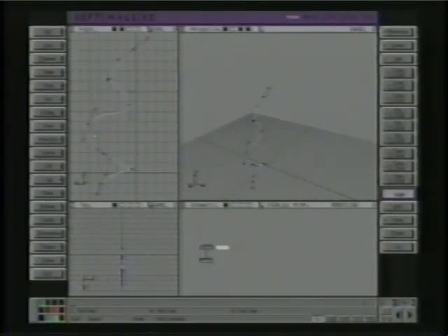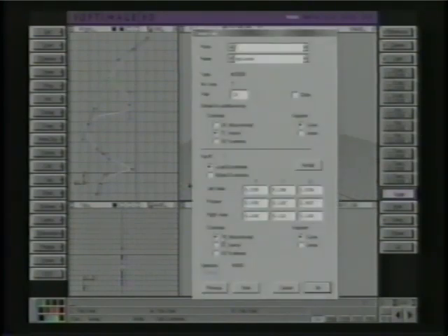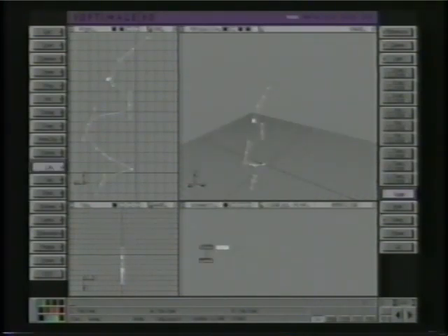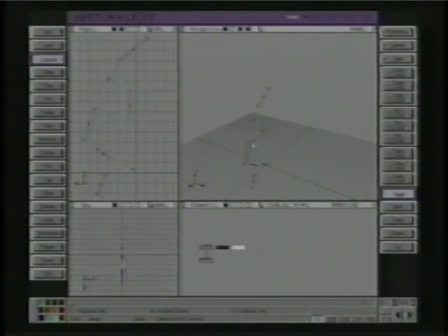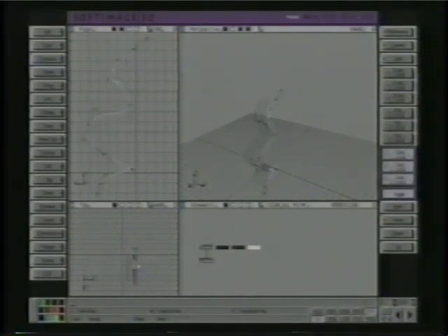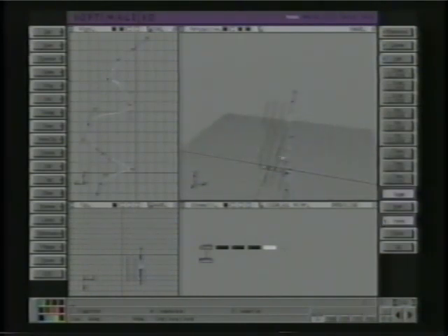The problems arise when you want to skin Beziers. There is no Bezier format in a skin, truly. There are some other oddities. For instance, if you go to Edit Coordinate, let's make sure that this one is discontinuous and make that into a definite hard edge. So drag those like that. Now if I want to duplicate this, and I want to drag this over like that, duplicate, drag. I'm just using the D hotkey for that. Now we have a couple to skin.